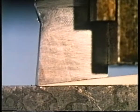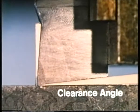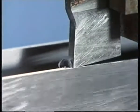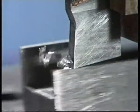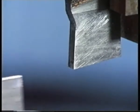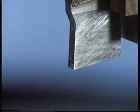Here's the angle between the bottom of the tool and the work, the clearance angle, and here's the angle we've just formed. It's called the rake angle. And let's try taking another cut. This time the chip seems to form in a much better way. But it's worth a closer look, again in slow motion.